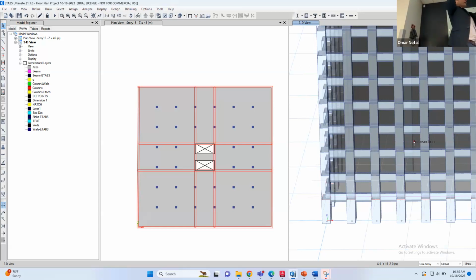So you draw elements like this until they connect and keep doing them like this, story by story. Like basically you will have 2D like XZ view, and you keep drawing an element here, element here. Once you draw them, you will draw one line of the bracing. You do it from the other side, they are going to be connected together. So you will do it for this side and this side for the 4 sides. So that you have all the building is braced. So this is how you build the geometry.